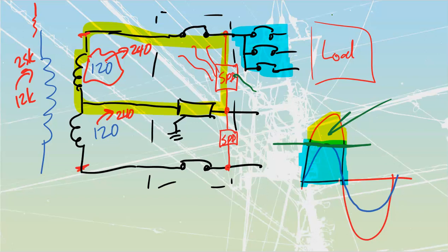We can sometimes have lower energy surges that come inside of our building that we ourselves create by accident. Sometimes they're going to be off of components that work with high electrostatic voltages, so photocopiers, microwaves or laser printers are common places that we will see these. The other ones are going to be my loads that are going to get driven.